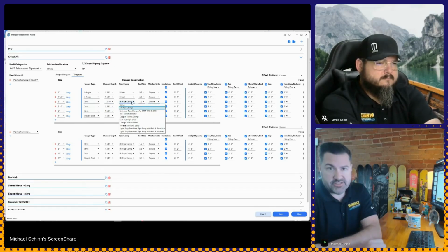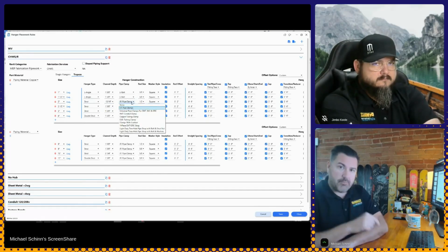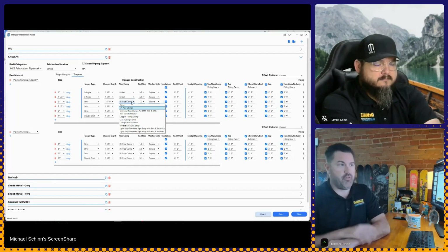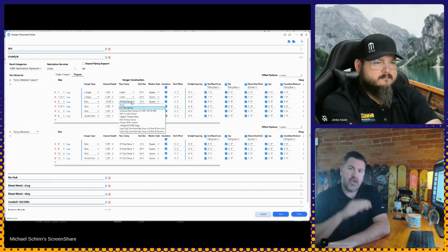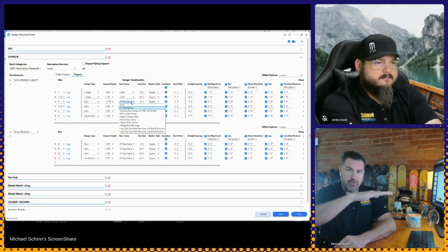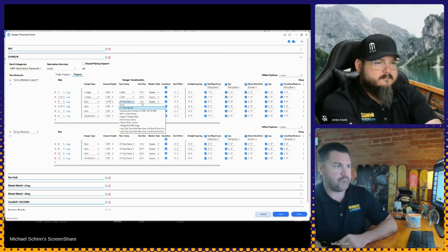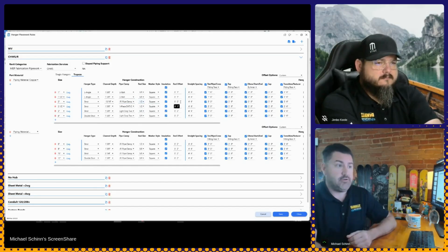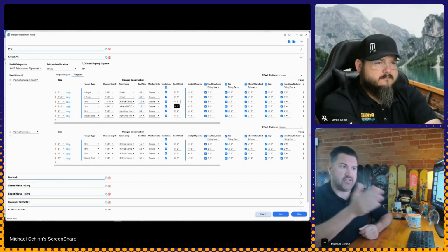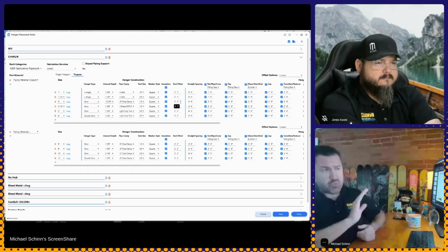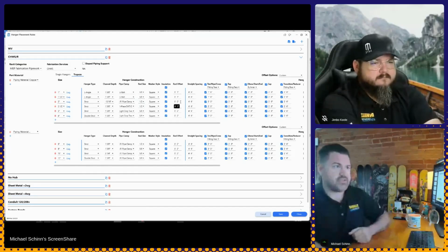Here's something that no one else is doing in the industry that I've seen. Automatically placing of your pipe clamps onto those hangers. And when those get placed, I don't want them to be just floating around. When I move those pipes around, I also want those pipe clamps to be smart and reactive with them. What size hanger do you want? Insulation, rod offset, which is the center of the rod to the face of the pipe or that piece of duct, how far off that little spacing is going to be.